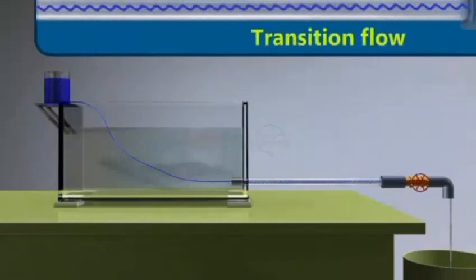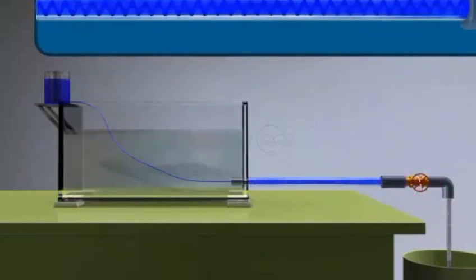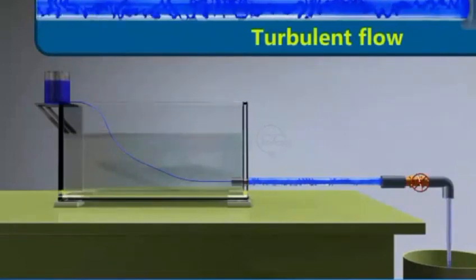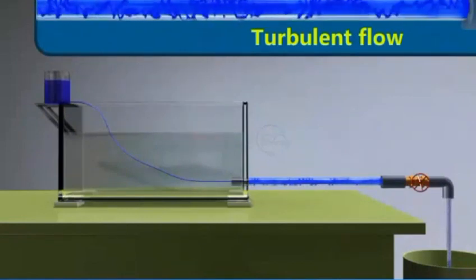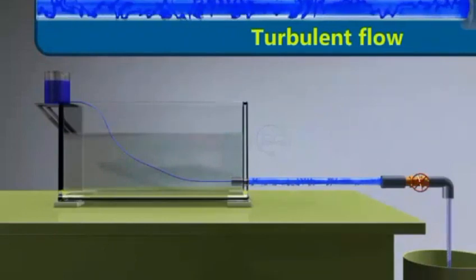We can observe that in these regions the oscillations in the flow were unstable and any disturbance would quickly disappear. Now fully open the output tap and observe the flow of ink through it. As the water flow rate was increased, a definite velocity called the critical velocity was reached. Oscillation appeared in the thread, and the thread of the colored water became wavy, gradually dispersed, and the entire mass of the water in the tube became uniformly colored.